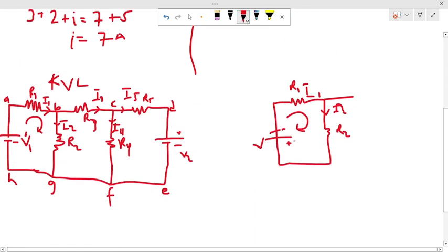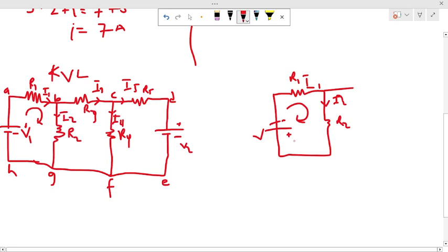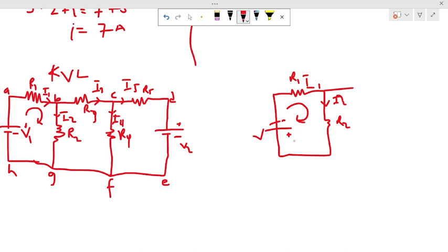Now let's move on to Kirchhoff's voltage law. The Kirchhoff voltage law has a lot of technicalities behind it. The voltage law states that in a closed path, the algebraic sum of the voltage sources equals the algebraic sum of the voltage drops. What do we mean by voltage sources? The voltage sources are the batteries and things that offer voltage to the circuit. For example, in this case, these are the voltage sources. So the summation of all of them will be equal to